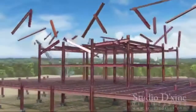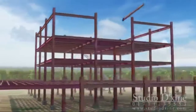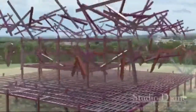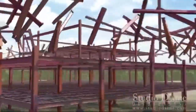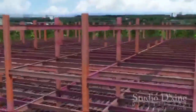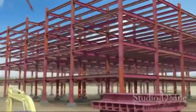Although for these reasons and manufacturing processes, steel beams come at a greater cost than concrete or timber. I-beams are also sustainably friendly as they are made with little byproducts and can be made from scrap metal, reducing raw material collection. I-beams are used specifically as the web section resists shear, whilst the flanges resist the bending moment. I-beams are very efficient in resisting these forces whilst maintaining lower weight, cost and cross-sectional areas.